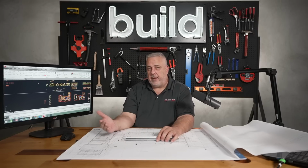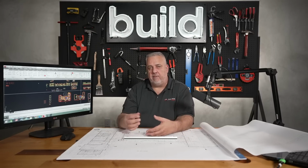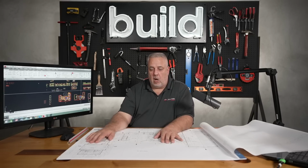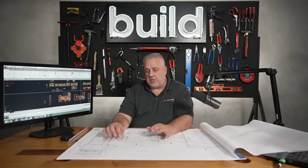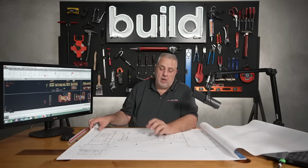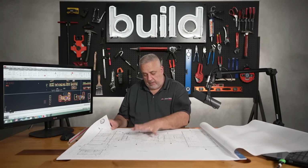As we go up in detail, the scale changes and becomes larger because we need to see a little bit more of the building. At 1/4 inch scale, we're just basically looking for the wall layout, the layout of the rooms, the location of the windows, the sinks, toilets, all of that information, which can be handled by the dimensions. In this case, the first floor plan is the first one we show because that's probably the sheet that gets referenced the most in the drawing set.